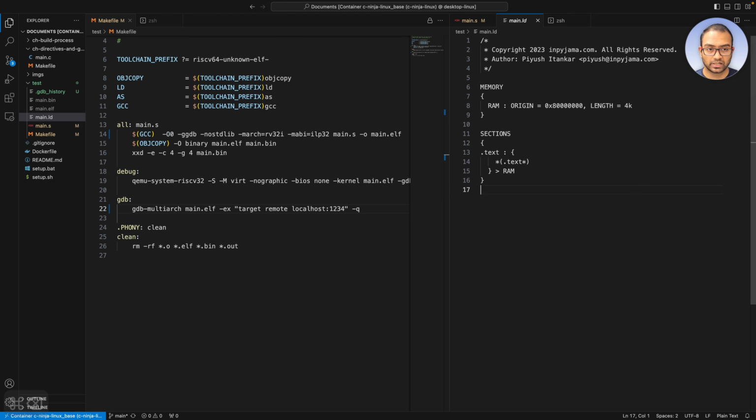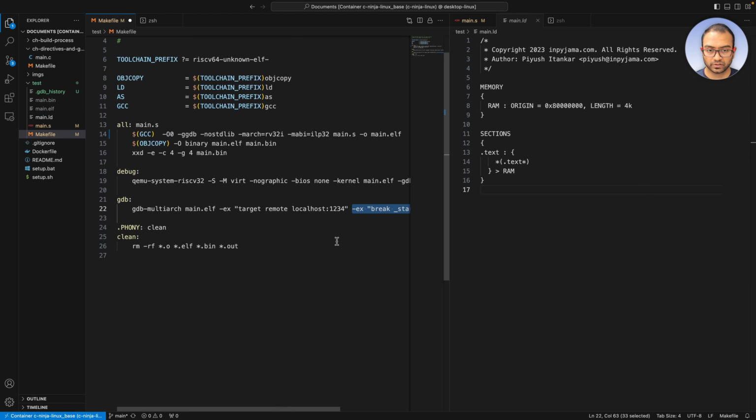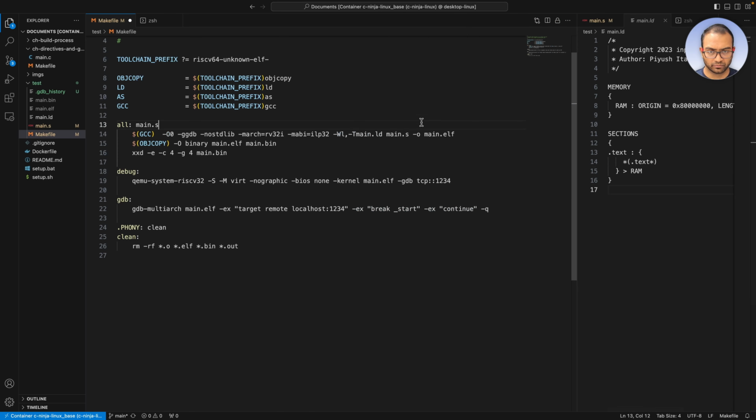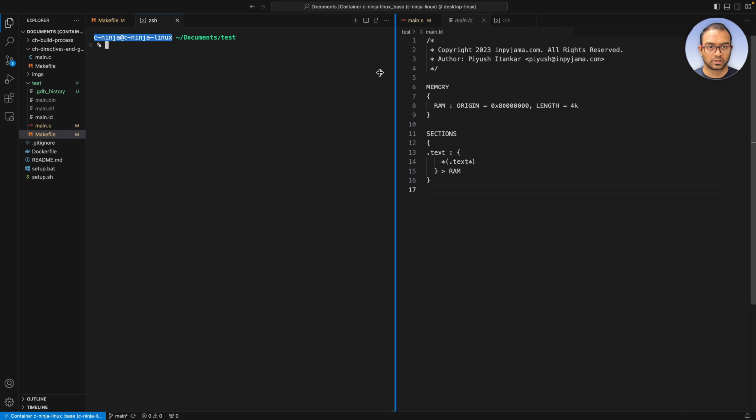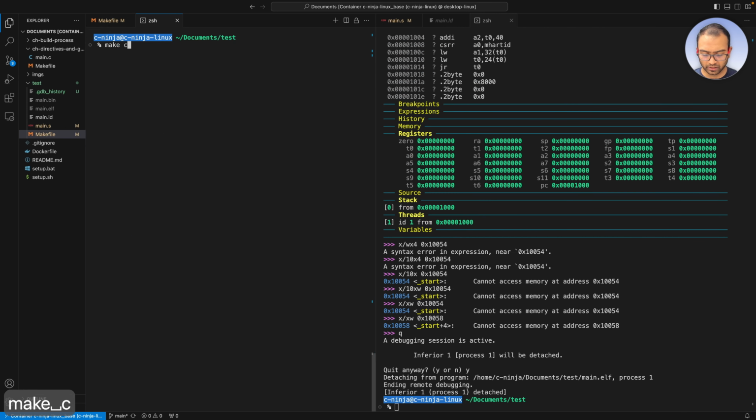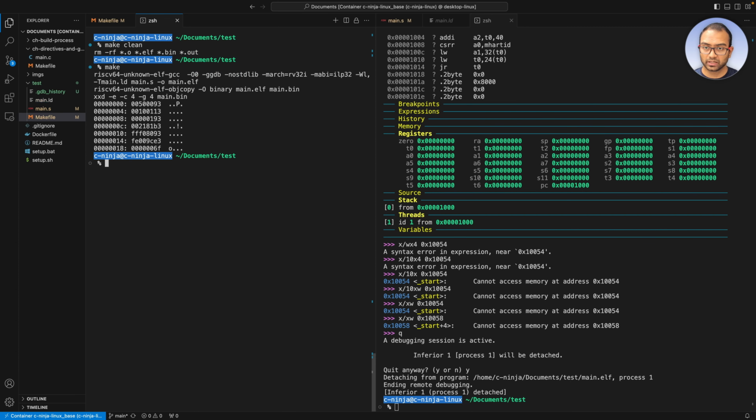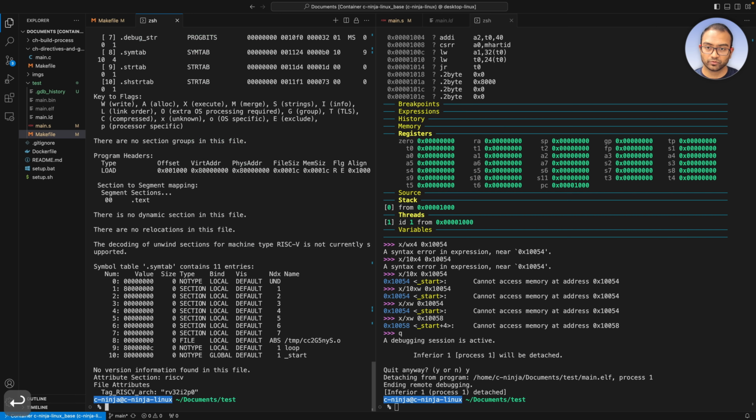Okay, so now let me go ahead and undo all of the things here. What I have undone is what was added here, and this is added. This will delete again, just so that we can see the jump from the ROM code once again. Okay. Right. So I'm going to save this file. Again, we are providing our own linker script now. Go back to the shell here. Then do a make clean. Then do make. Now we are going to do a readelf again to confirm a few things.